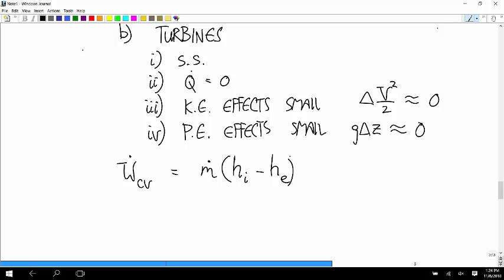It has to be bigger at the inlet because we know W dot has to be positive, okay? And it's bigger because there's a high pressure at the inlet and a low pressure at the exit, which also corresponds to the sort of counterintuitive fact that, at least usually, the speed is faster after it's gone through the turbine than it is right before.